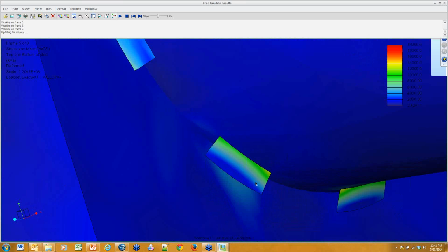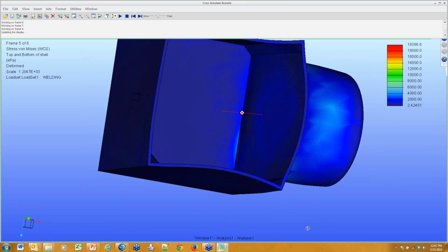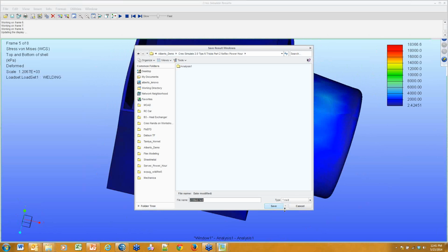I only did a single pass adaptive. In this case, you might want to increase that to multi-pass adaptive so that we can get some additional accurate loads. Right now, the meshing is very, very light around these areas here. But this is giving us enough foundation to actually create our next feature. Let's close this up.